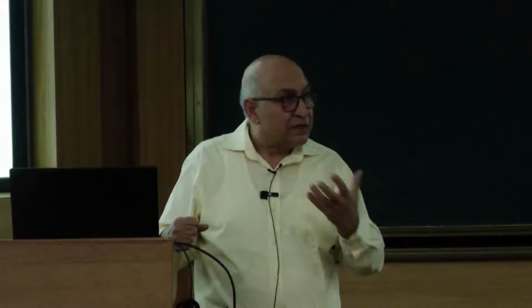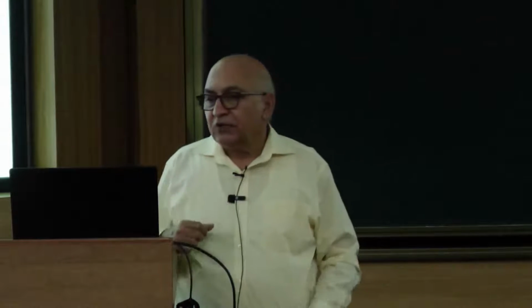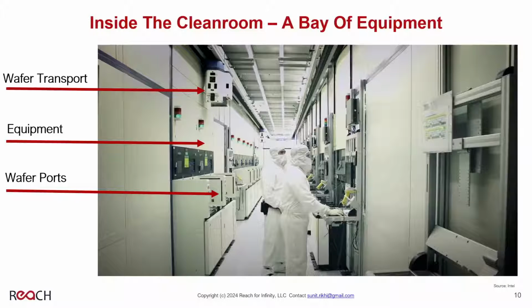So that's the only way to interface what needs to be processed or what has been processed. Those are called wafer ports. And then above, you will see in the ceiling, there are these wafer transport robots that are coming in. They stand on top of the load port, or wafer port, and then they lower the material into it, and the tool takes it. And I'll talk about that in a second.